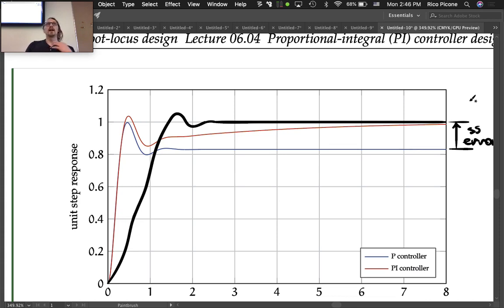So you're going to have to trade off between your steady state error compensation transient and your initial rise transient. It depends on the design situation. It depends on what you need out of the system, what the performance is. It wasn't really specified in our design problem here which is more important to us, so we don't really have a way to answer this question. But we just know that there's a trade-off here, and if you're designing the controller, you have to figure out which is better for your design. Does that make sense?